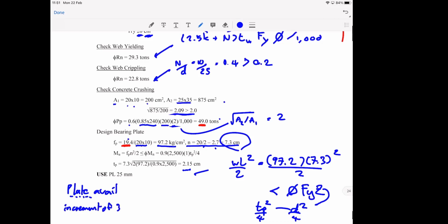So you can easily find the plate that is 3 millimeters thick, and then 6, 9, 12, and so on, until it becomes like 18, and then 20 millimeters, and then 25. Okay, so sometimes you want to use the most practical size and save money. So you would say, hey, can I use a 22 millimeter plate? You better check the availability of the market as well, because sometimes when you assign the size of the plate and they cannot buy it anywhere, they're going to have to change it in the end anyway.